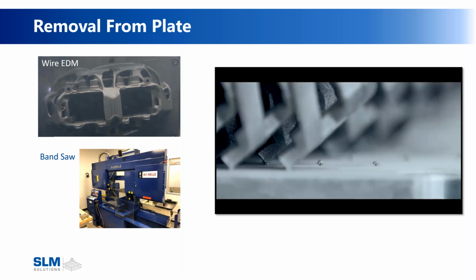The next one, bandsaw. Bandsaws are very quick compared to wire EDM. They're significantly cheaper compared to wire EDM. You don't have things such as wire and solution. It's just a saw blade and we're cutting parts. This is metal, so a metal blade cuts through metal parts. It still may take 20 plus minutes to cut through a big, thick section of a part, but it's an overall very cheap process. This is actually the SLM Solutions bandsaw that we have in our office that we use to cut our parts off.